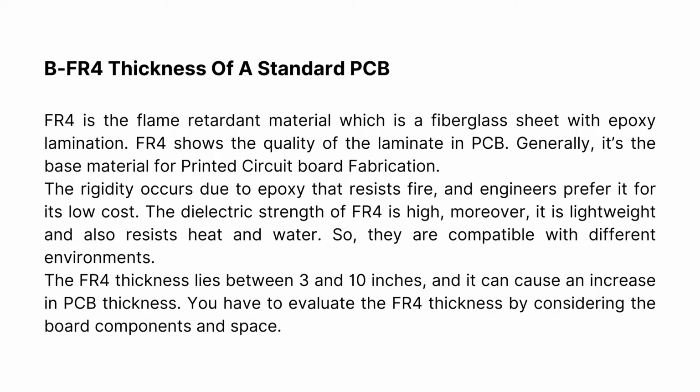FR4 thickness of a standard PCB. FR4 is the flame retardant material, which is a fiberglass sheet with epoxy lamination. FR4 shows the quality of the laminate in PCB. Generally, it's the base material for printed circuit board fabrication. The rigidity occurs due to epoxy that resists fire, and engineers prefer it for its low cost.